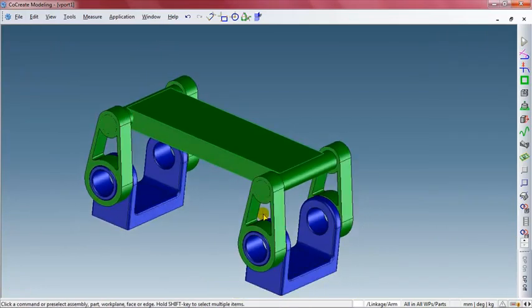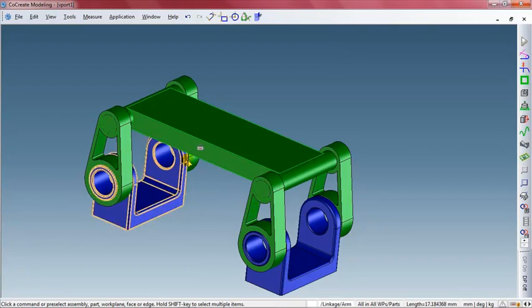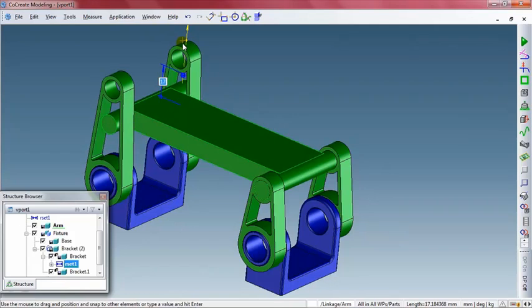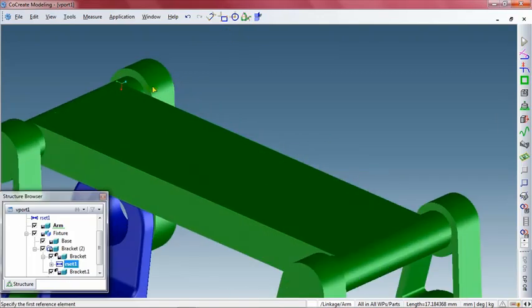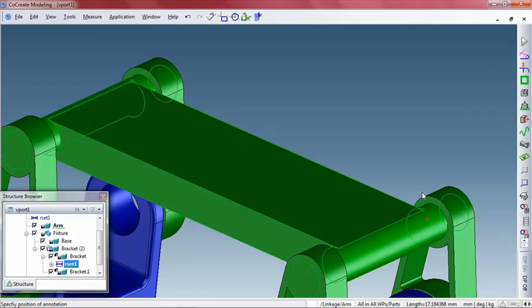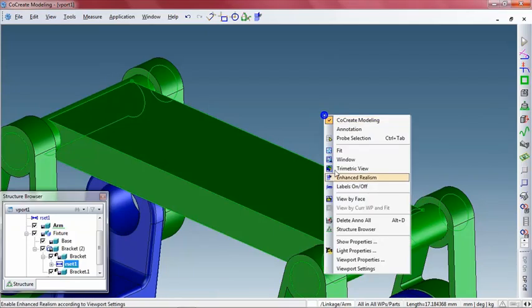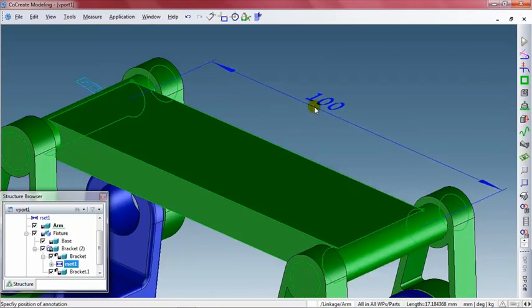After analyzing our 4-bar concept design, I want to change the motion in our linkage system. I can do this by stretching out the length of one of our bracket arms. As you saw before, I can modify one of the arms, and both change because they are shared. Before I make the change, I'm going to add a couple of dimensions to the assembly.